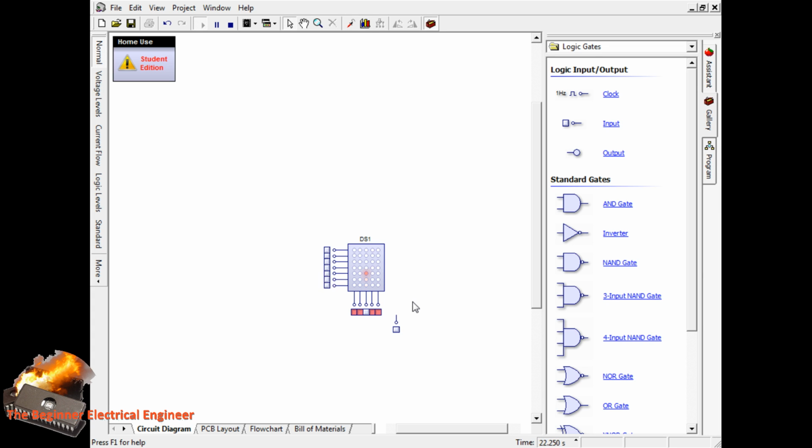Now, an example of doing this without multiplexing, an example of doing it the old way when they struggled before multiplexing came about, is you would have, say you wanted to make a letter I right in the middle, then it's nice and easy. You just turn on one column and all of the rows that you need to make an I shape.